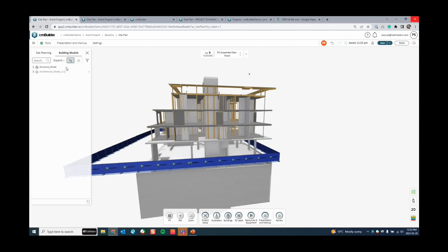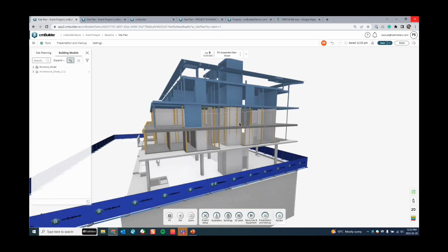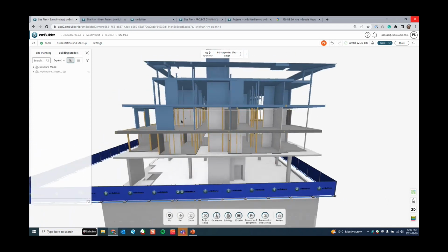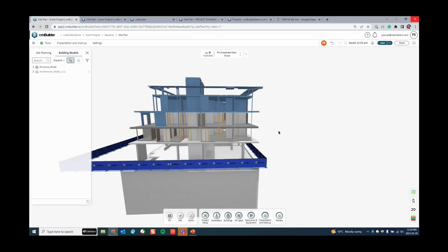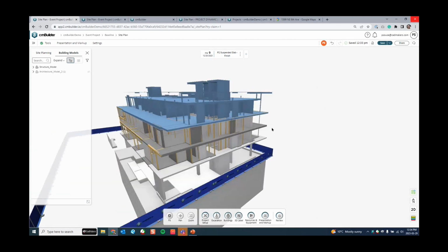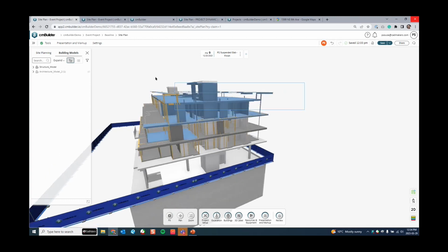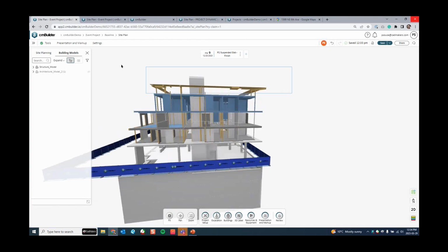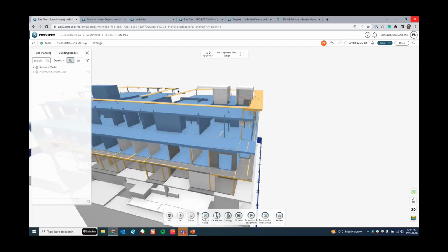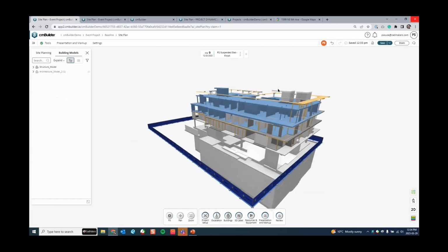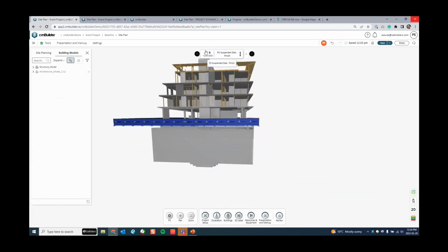Yes. So over here, I'm just highlighting my structure. So if I hold Control and select parts, and I accidentally selected parts over here that are in this lower level, now I can hold Control and Shift and unselect these parts. If I hold Control and click on these parts, I'll also unselect them, but the Control and Shift do a lasso unselection. Okay, cool. That's a mouthful.